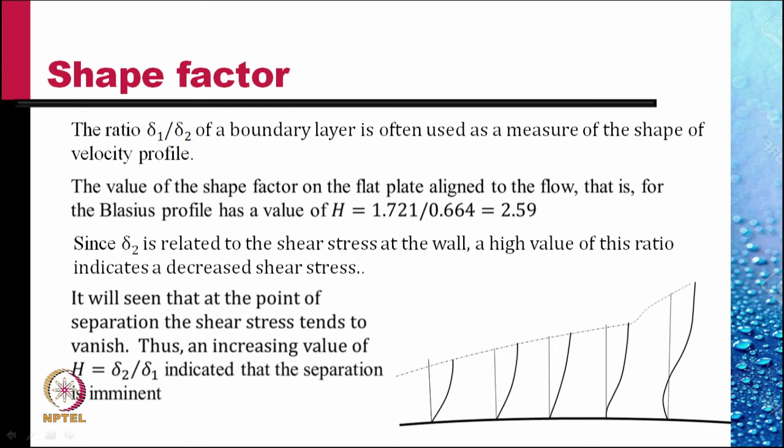It will be seen later that at the point of separation of boundary layer from the wall, the shear stress tends to vanish. Here on a wall, we have shown different boundary layer profiles. At this location, du by dy at the wall is 0.